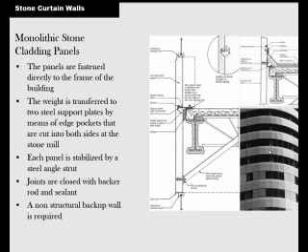Here's a building that is a stone cladding, and with a steel structure similar to the one we just saw with brick, but now they're going to use a stone system. Notice the drip edge even on the stone so that the water doesn't creep in there. And then here, the stone is pre-cut so that it'll snap into this for this particular system. This is the roof detail, because the stone will stick up past the roof, then you'll have this roofing material that's canted down and all this flashing so the water doesn't get down in there.